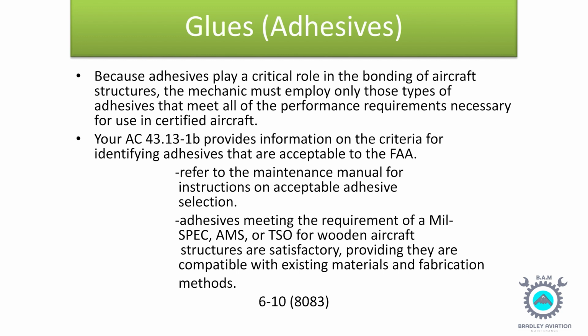Adhesives meeting the requirements of a MIL-SPEC, AMS, or TSO for wooden aircraft structures are satisfactory, providing they are compatible with existing materials and fabrication methods.